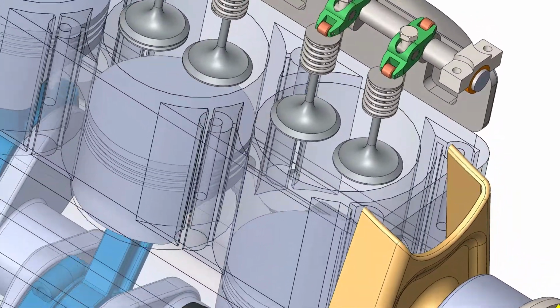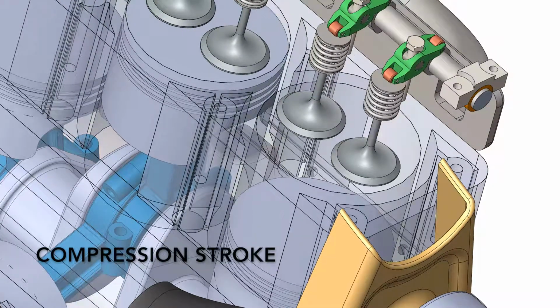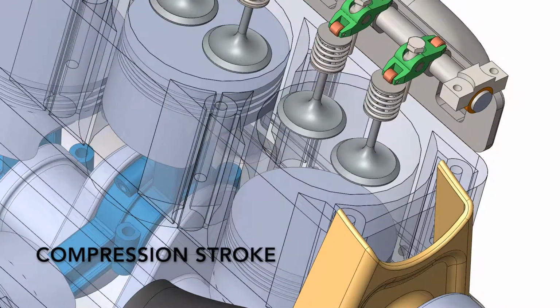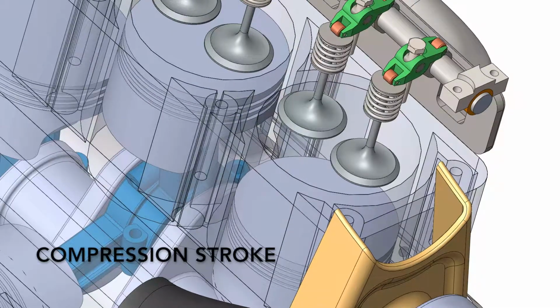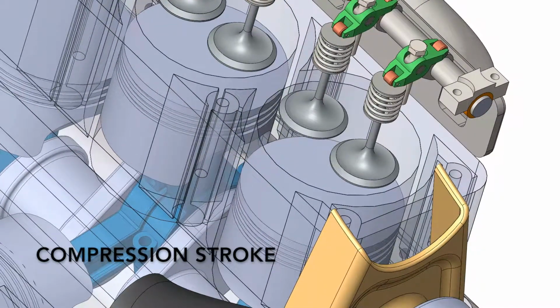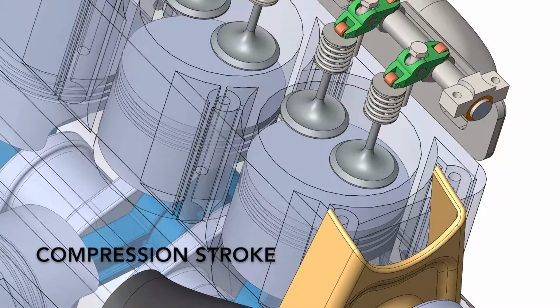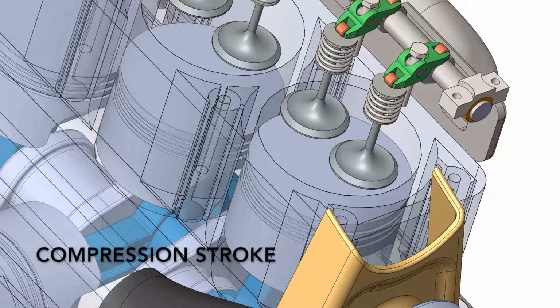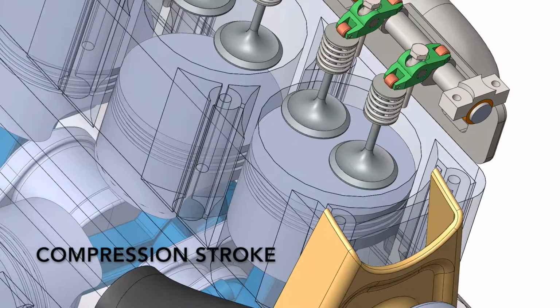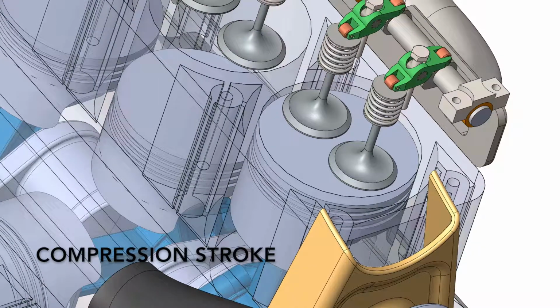The second stroke of the 4-stroke cycle is the compression stroke. The piston moves up in its cylinder, decreasing the volume and increasing the pressure. This compresses the gas that was previously pulled into the chamber. This process can be estimated as both adiabatic and isentropic as estimated by the reversible Otto cycle. The gas is then ignited with a spark plug and the pressure quickly jumps very high.